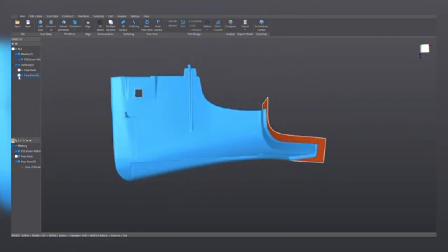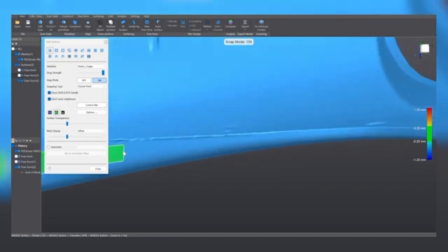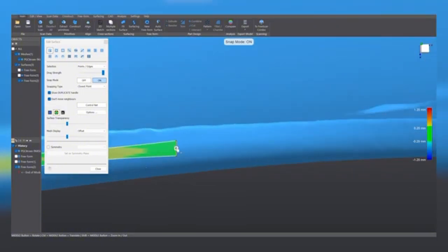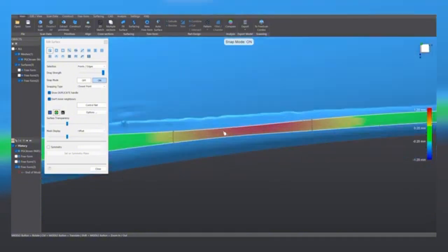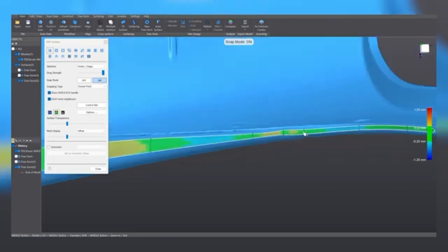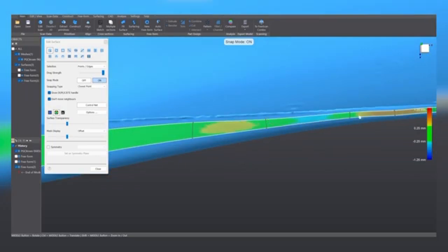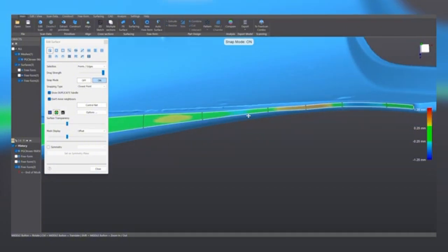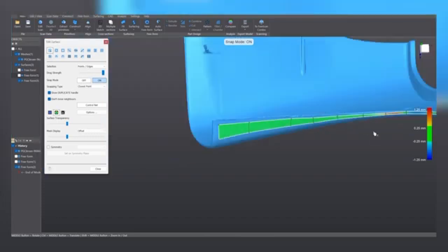And now let's do the same here. New freeform, snap mode is on. We snap this face here. And little by little, we reproduce the surface. Like this. Now here we have definitely too much error, so what we can do is splitting this face to have some extra resolution, and now adjust the surface a little bit more. Like this, and actually we could even give it some extra resolution here.